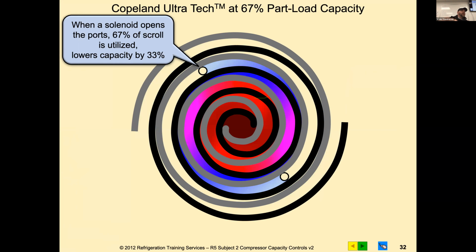There's two little holes in there where it's bypassing the discharge valve. As those two discs oscillate, it opens up two ports. That unloader ring slides really ever so slightly in one direction and opens up those ports. And then when you de-energize it, it's spring loaded. It returns back to plugging those two ports.